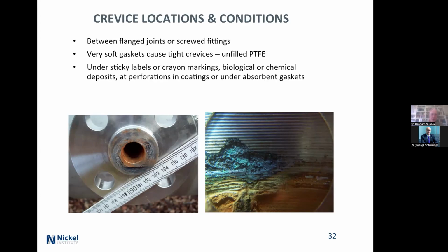Other ones, sticky labels aren't too good, crayon markings, biological growth, chemical deposits, perforations. The perforations at coatings, people spraying carbon steel on offshore platform, and some of the coating drifts in the wind and lands on stainless steel, and they wind up with corrosion around the edge of that blob of coating. Or under absorbent coat gaskets, that's just bad news because it stays wet for longer too.